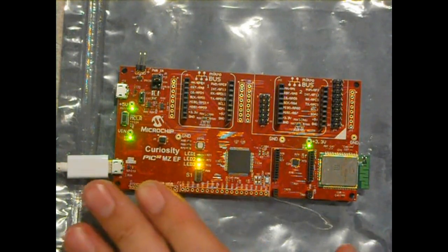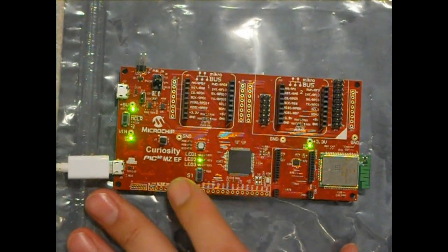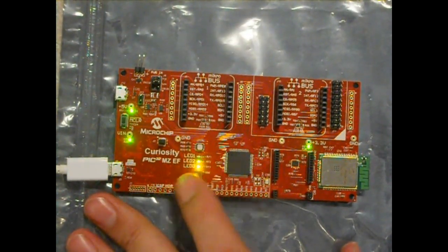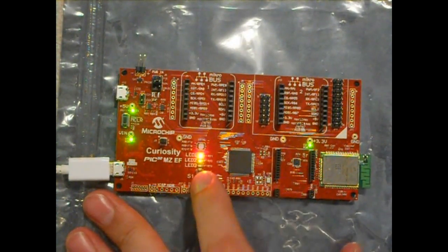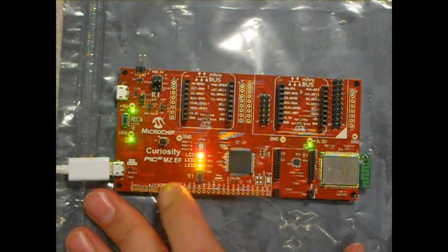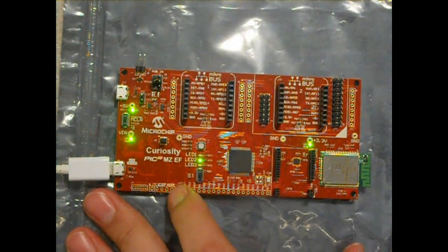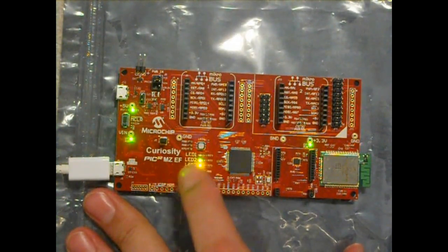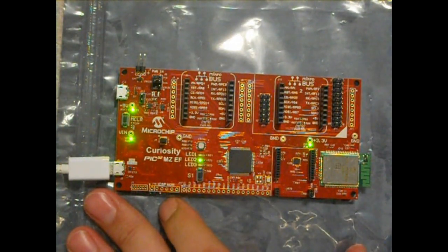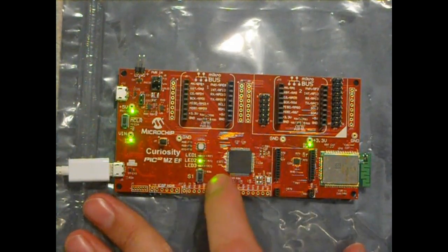So it runs 20 million cycles, turns it on, runs 20 million cycles, turns it off, and that's basically what we got. So when we push this button, it's not going to be as responsive as we probably want, and the reason is that we have to hold it on at least for one flash, because there's only one line of code that is checking to see whether or not it's on or off, and there are many cycles because of the delay code that run before or after. So we are only checking at one very specific point in the code.